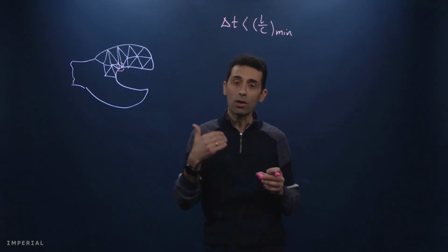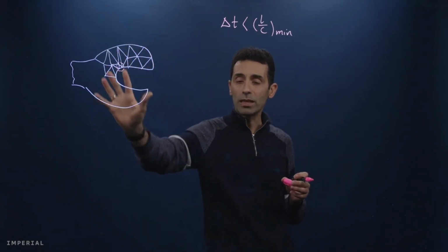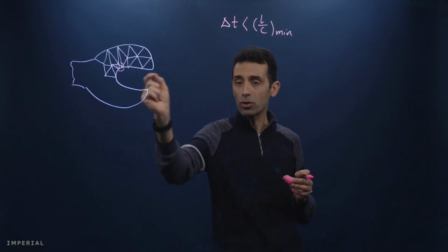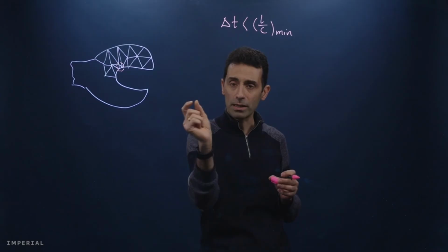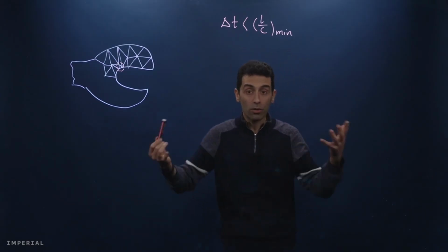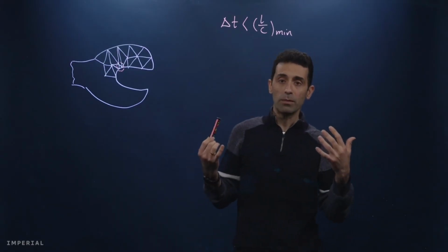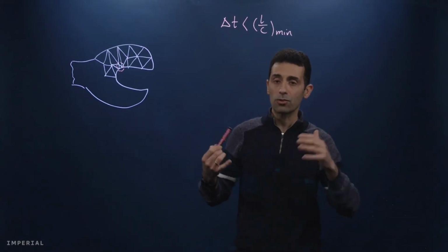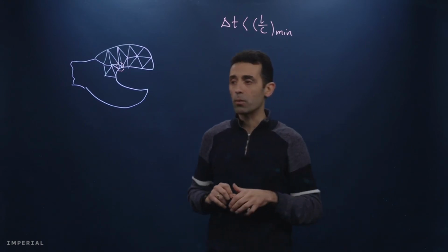Hence, you can go and toggle, you can remove those edges and make sure that the mesh generator is not constrained by those lines. So it doesn't have to put an element across those two lines and therefore create such small elements. So you can look across your mesh and try to remove those small elements by removing the geometrical constraints and remeshing your structure. So that's method number one.